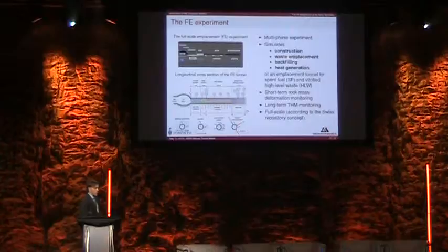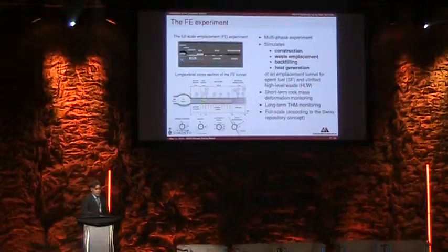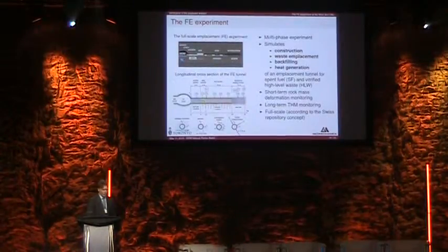The rock mass response during the excavation was monitored using different tools, including measurement of the convergence of the excavation perimeter, extensometers, both in direction parallel and perpendicular to the bedding, as well as some inclinometers in the crown. So this is a perfect case for calibration of a numerical model of this type.